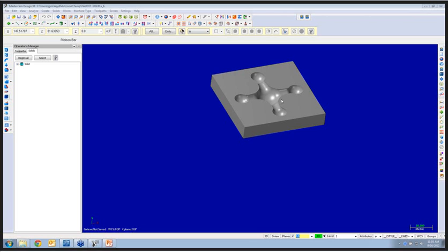But we'll let you reference the points of an STL file, draw in curves, draw in lines, and connect those together using the main tools that I showed you. You're just building or hanging geometry off mesh files. You could call it mesh morphing, or there's a number of terms people use for it. But you're just building geometry based on a picture that you see on the screen. And so we do handle that.